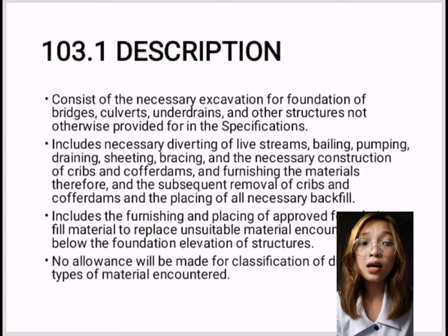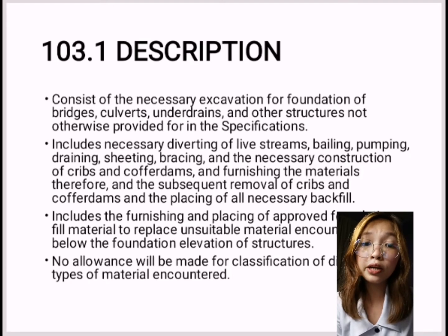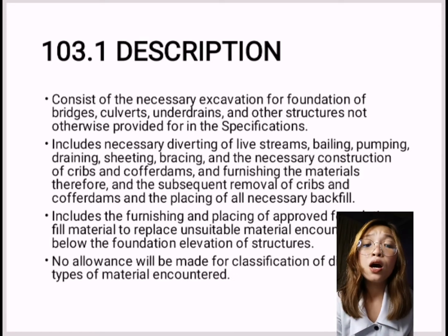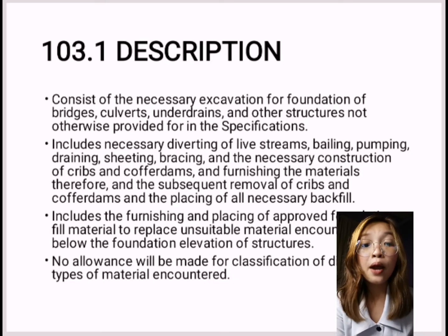So, except as otherwise provided for pipe culverts, the backfilling of completed structures and the disposal of all excavated surplus materials shall be in accordance with these specifications and in reasonably close conformity with the plans or as established by the engineer.